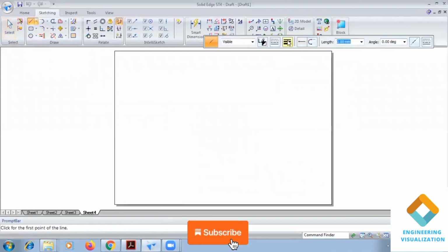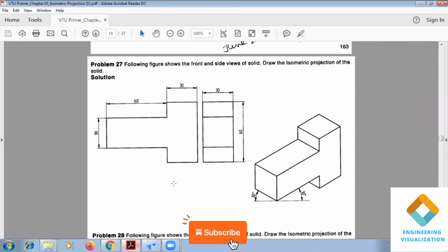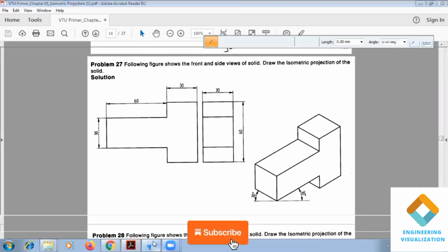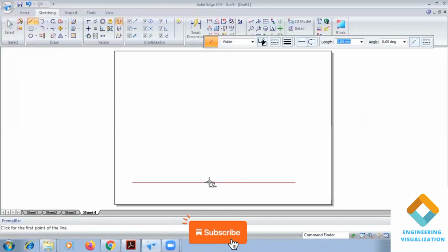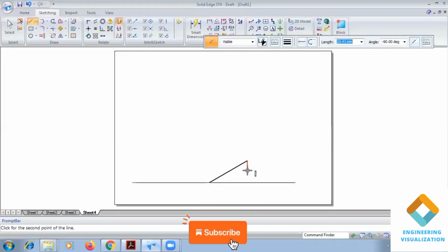First we take a reference line. So from this end, construct 60 length, angle 30. Next it is vertically downward by 15 mm. So downward 15.